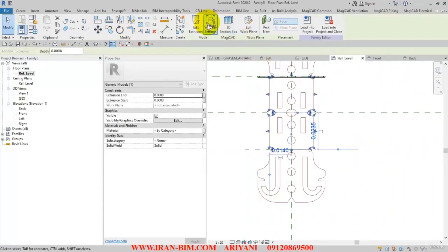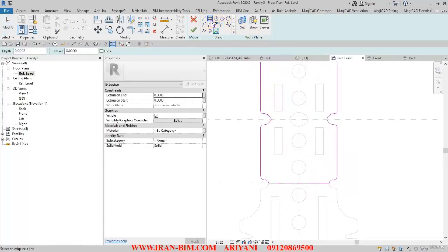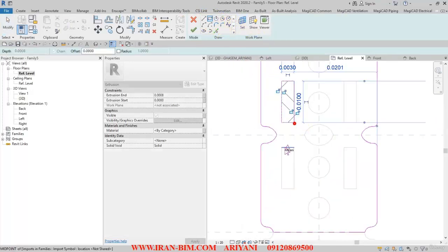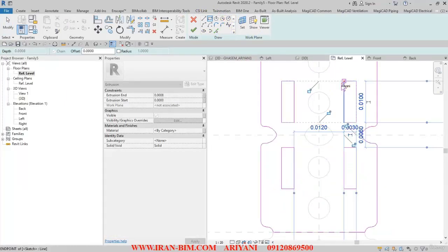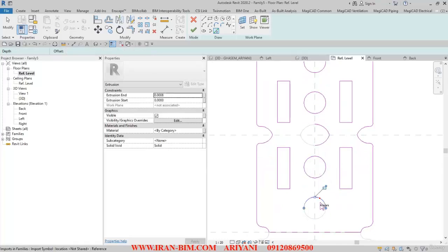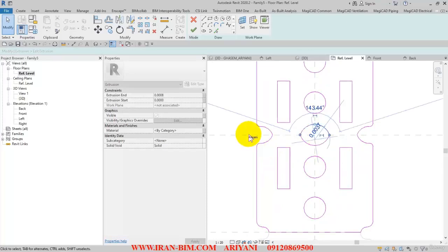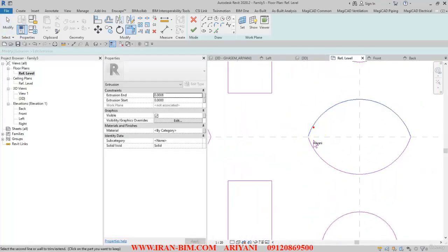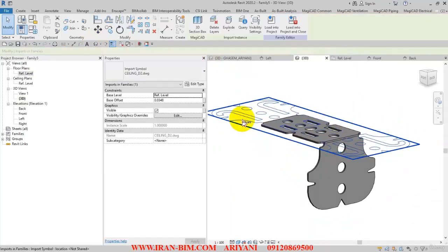And then click on edit extrusion, and then I'll draw these rectangles that we have in the middle. So there is this one, and then this one, and after that we go to the circles in the middle, draw these as well, and then this one as well. So try to keep the amount of sketches as low as possible. You don't need to draw many sketches, just draw this one and then connect it here. And then finish this, and then we go back to this view.